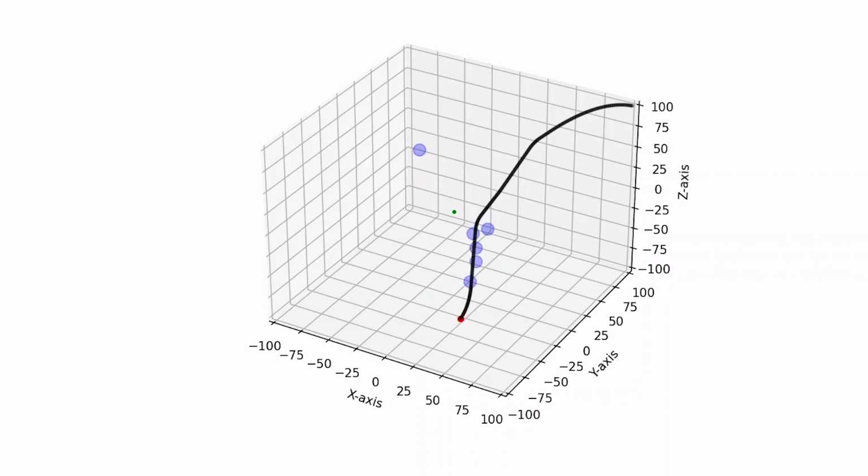In avoid mode, the algorithm uses system dynamics to calculate a discretized set of reachable velocities within a time step. The velocities which lead to collision within a specific time horizon are eliminated, forming the set of reachable avoidance velocities. From this set, the velocity closest to the current velocity is chosen to ensure collision is avoided and course deviation is minimized. The algorithm was first tested in a basic Python simulator, then tested in JMAVSim, a UAV simulator.